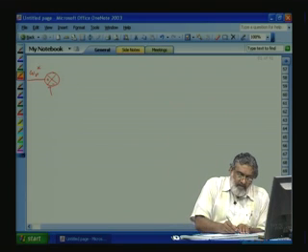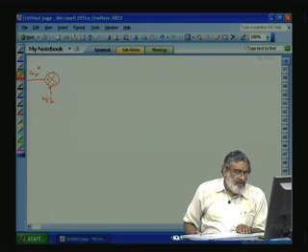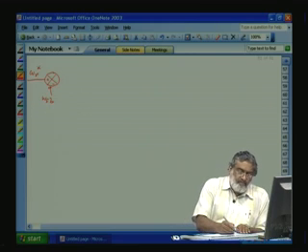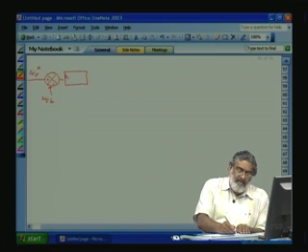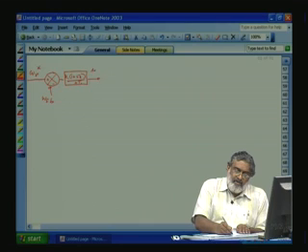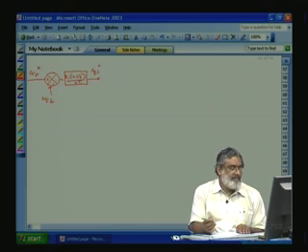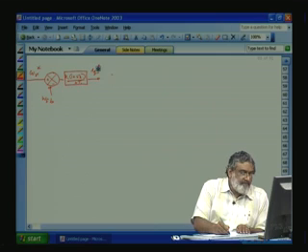And this is the omega feedback. Okay. So this will give to a speed controller, PI controller, so that we will make it as K1 into (1 plus ST1) by ST1. This is the PI controller. This output will give our IQS star. Okay. This IQS star